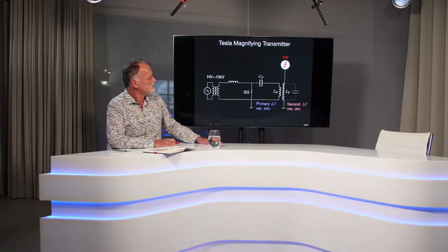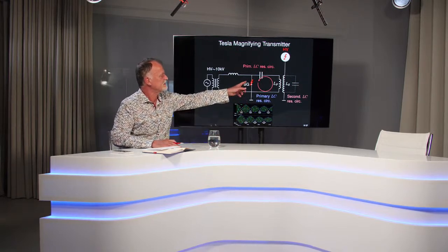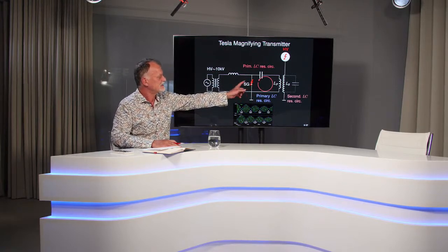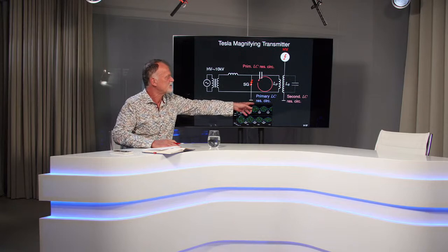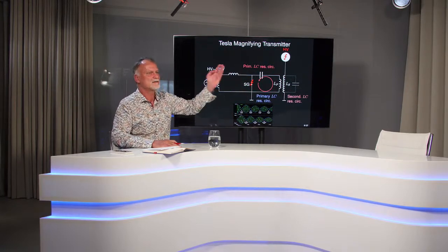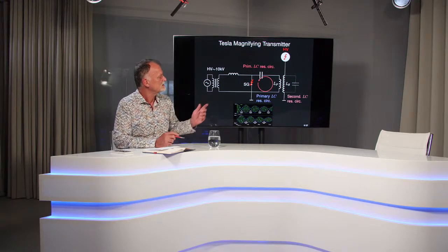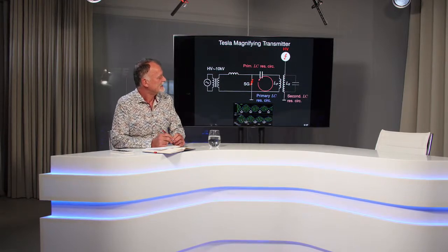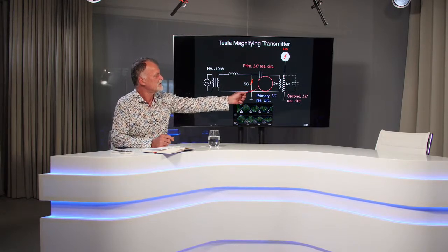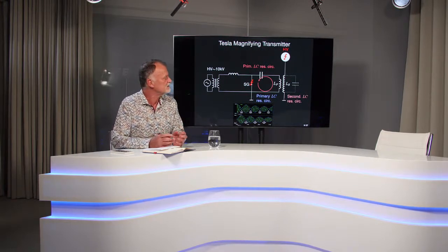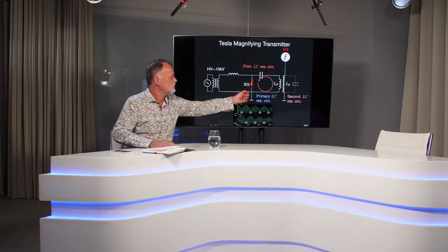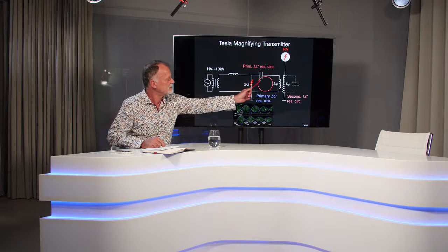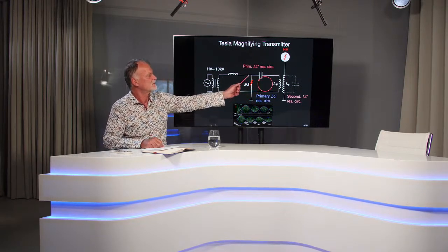So if we go to next slide, please, at the moment the sparking gap gets shorted, you have an isolated LC circuit, we call this the primary LC resonance circuit, with the primary resonant frequency, right? This is typically tuned by the value of the capacitor and the coil. And if the secondary coil is tuned to the same or a similar frequency, then the energy stored in this system, which is typically a couple of joules, is transferred to the secondary circuit and back and forth, right?